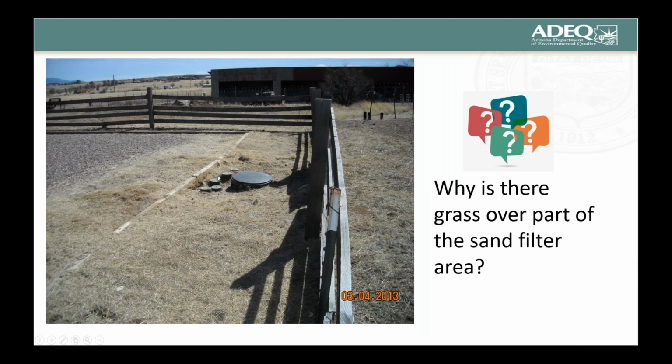What we found out is that one of the zones, the connecting pipe to the zone, was broken. So when this rotating valve got around to supplying effluent, it discharged the effluent through this broken part and flooded this whole area, and of course the grass went where the water was, and it proceeded to grow. There was some water in the natural course as well, so it encouraged the growth to move toward the east into the disposal area.